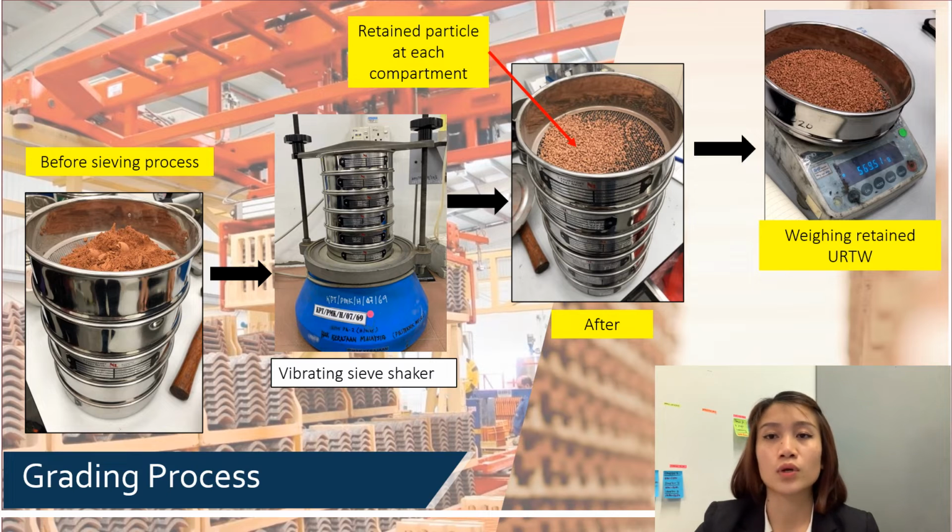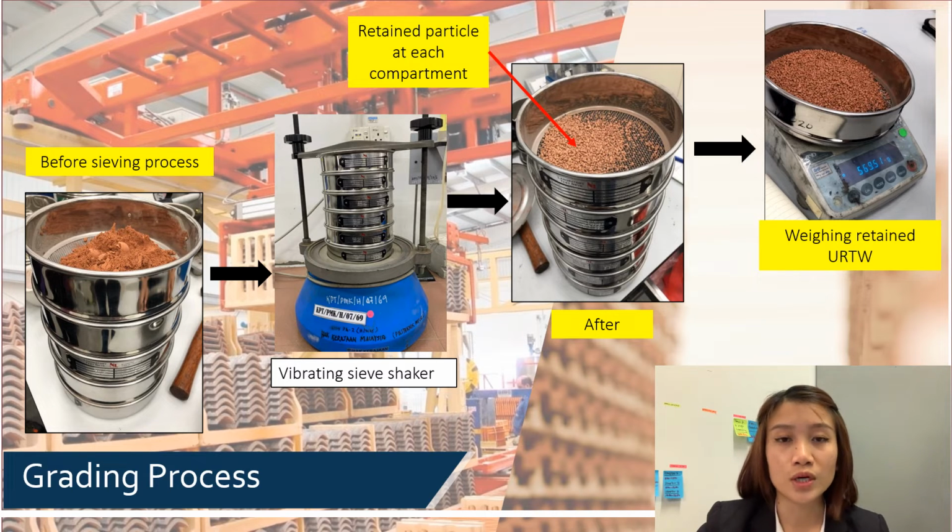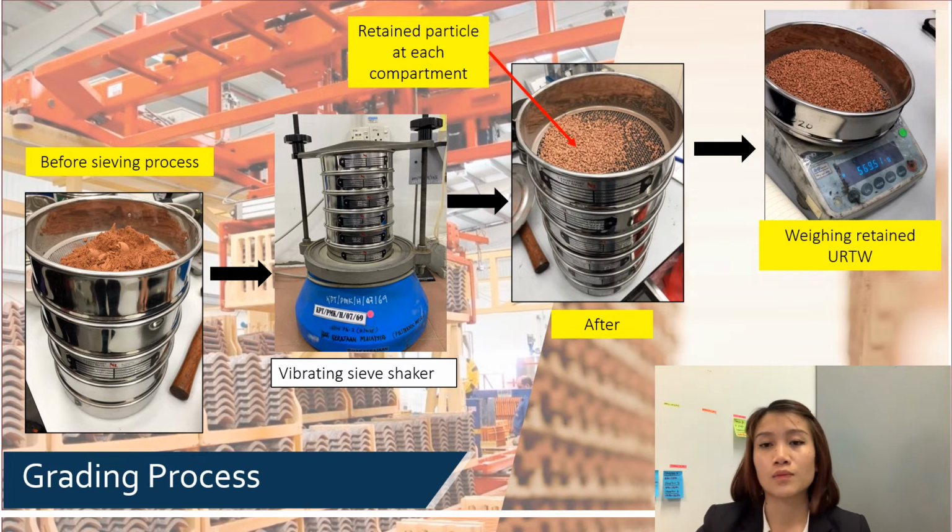The sieve shaker will run for 10 minutes, and after 10 minutes the sieves will be opened up, and each of the stack will have retained particles at each compartment. The retained particles at each compartment will be weighed to be recorded and analyzed.